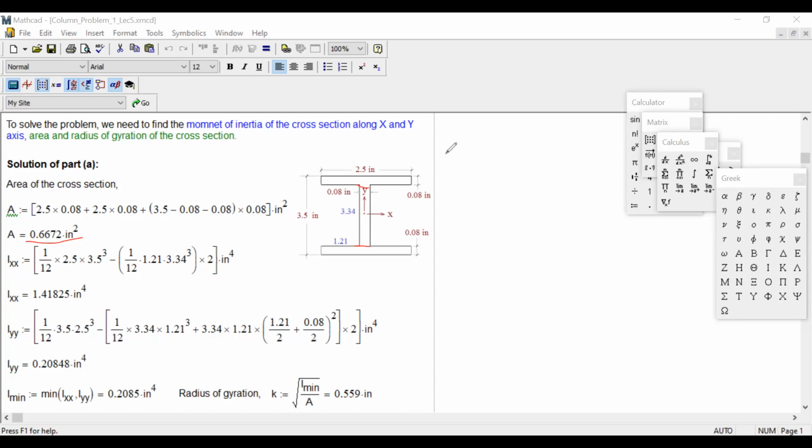So how will we figure out the Ixx? You already know from your solid mechanics class. Okay, so I will use the simple way. We are taking Ixx and Iyy. At first, I like to figure out Ixx. So if I take this bigger portion, bigger block, for rectangular cross section, the inertia is 1/12 BH cube.